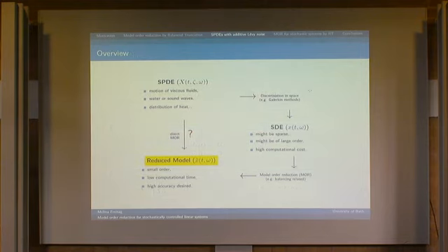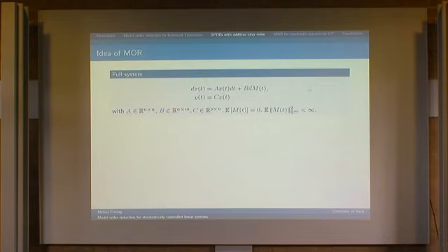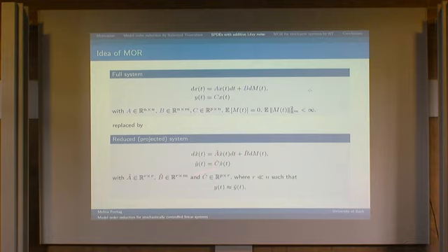Okay, what you do is you reduce the system using balanced truncation. In this case, but there are other methods as well, so this is not the only method. This is just a method that is sort of related to this observability and reachability idea. Okay, so I've got this system, and what I want to do is reduce this to this system. I basically want to find these gradients again, the observability and controllability gradients.